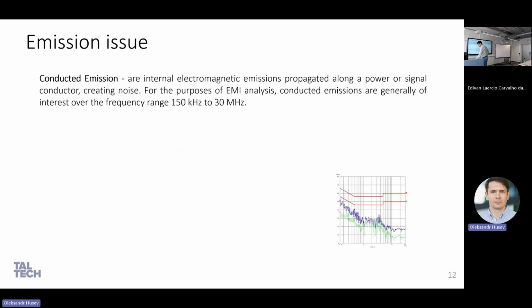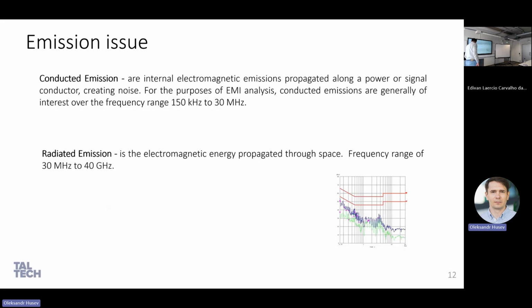Okay. So now about standards, because formally I have to. If you are talking about it, we have to specify that we have conducted emissions, right? That actually range from 150 kilohertz to 30 megahertz, and it's caused by a real mechanical connection of conducting elements. And radiated emission, because electromagnetic energy propagates through space, and here the frequency range starts from 30 megahertz to 40 gigahertz.